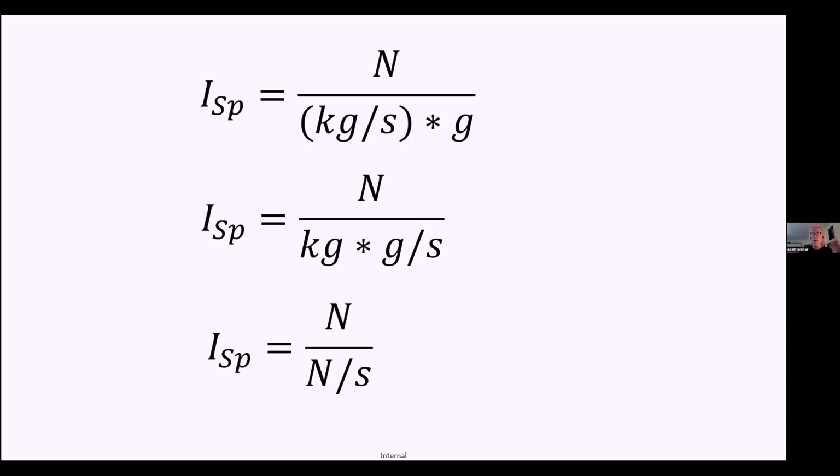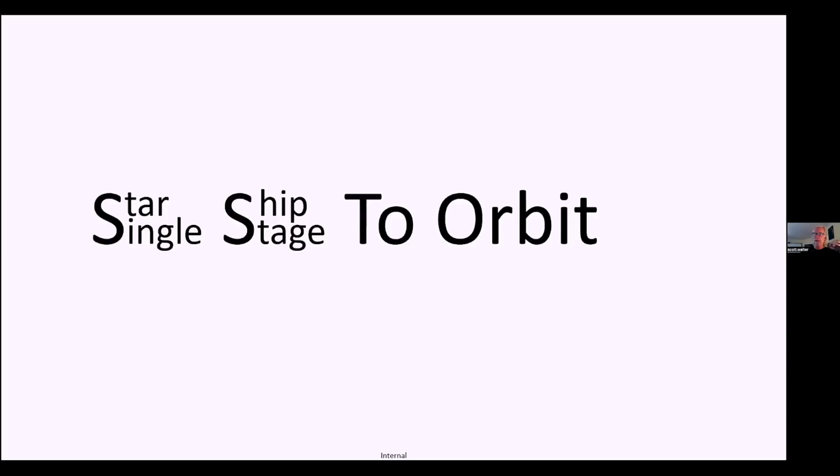There's two forms of the rocket equation. One that uses what's called effective exhaust velocity. And the other is using ISP, where ISP is multiplied by g sub c, where g sub c is the gravitational constant on the surface of Earth, to convert it into effective exhaust velocity. So they're basically one and the same thing. And that's why ISP is what it is. But now the question is, what does it mean?